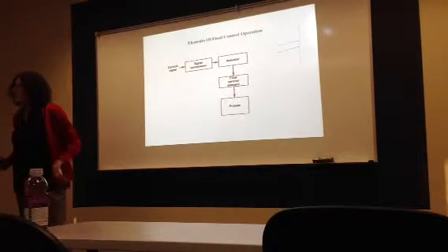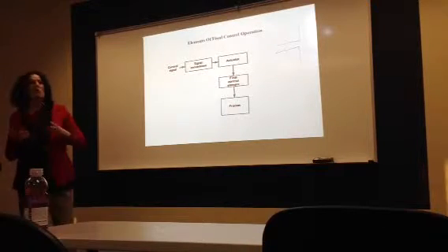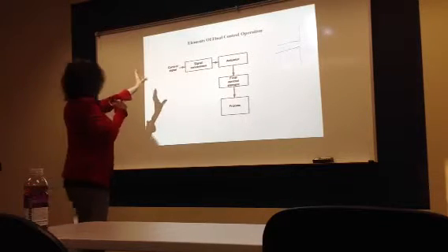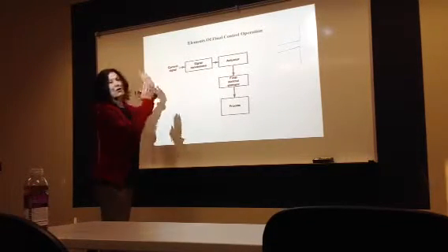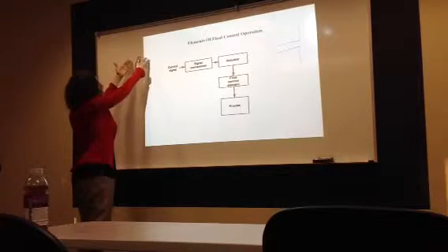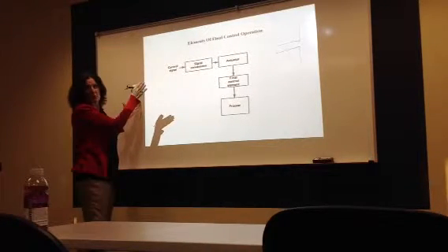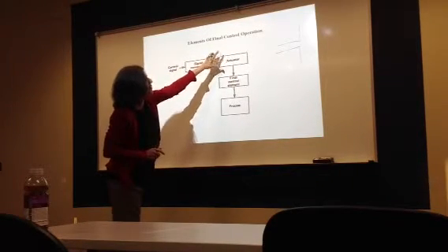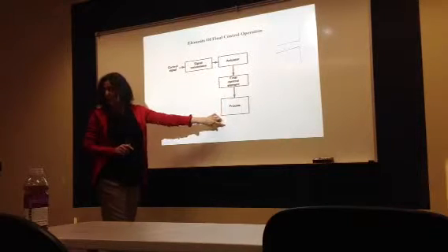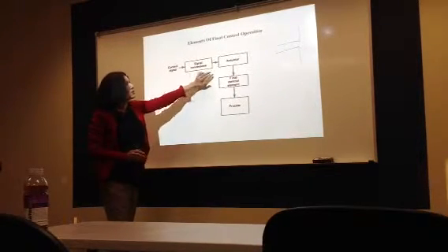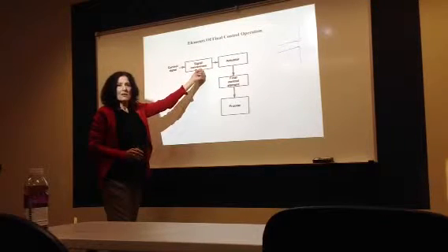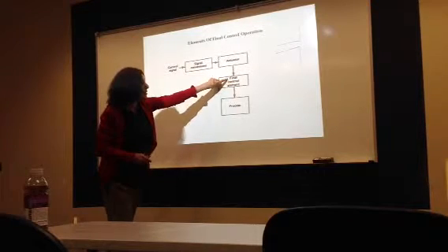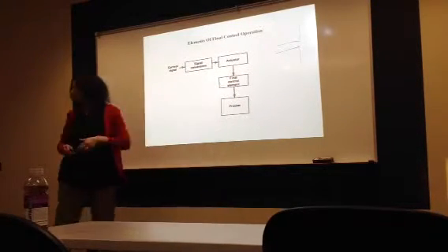Chapter 3, we started to talk about the elements of the final control element. So we started now to talk about the control signal going from D to A. Here we're going to start with the digital to analog converter. So when we go digital to analog converter, we're going to send the signal to the actuator, then we're going to send it to the final control element. So you have to know all these definitions. What does actuator mean? It takes the signal from the controller, switches it to action to activate the final control element, and then changes the process. All of that you have to know.